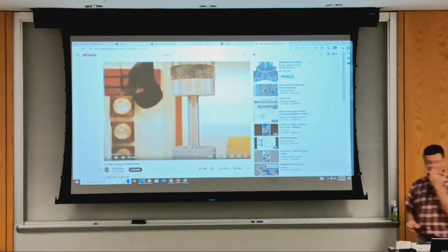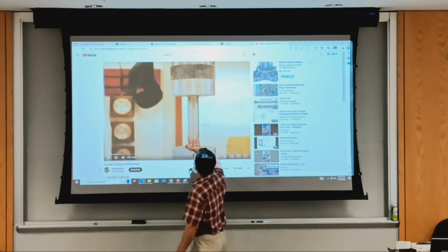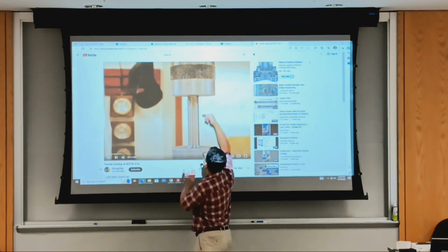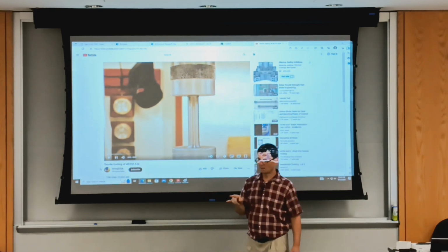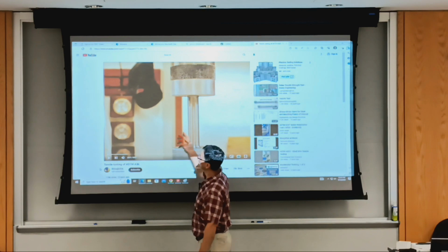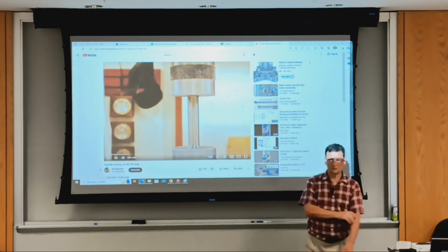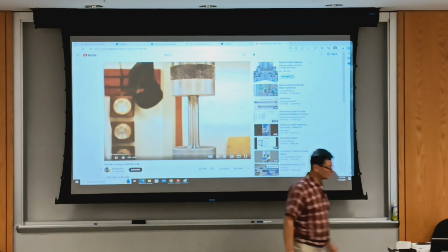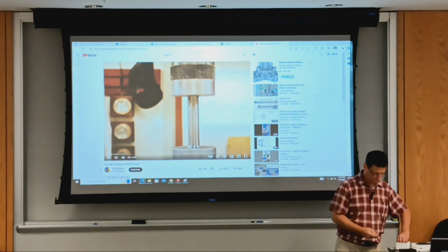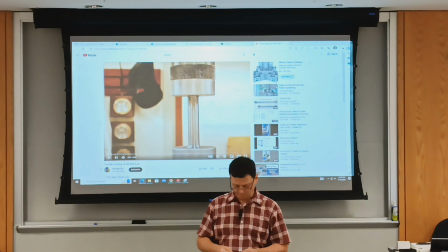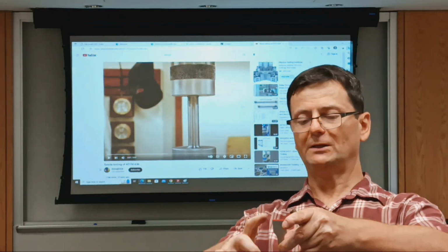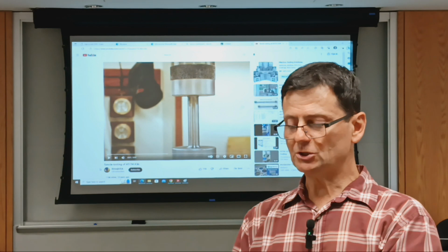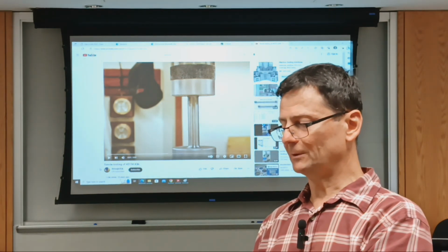Okay, so this is a tensile machine, and this is how the specimen looks. It's standardized. Length is 5 inches, and diameter is 1/2 inch, with good finish, not apparent roughness. They also do specimens for sheet metal. Okay, so this is an aluminum piece. Yes, it's an aluminum sheet metal, and originally was 5 inches. It got stretched before it popped, and just observe the way the fracture happened. It happened at 45 degrees.